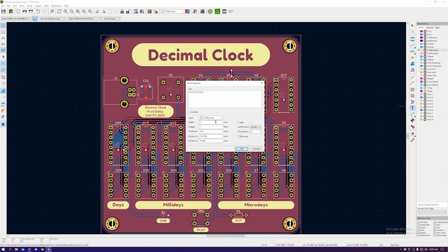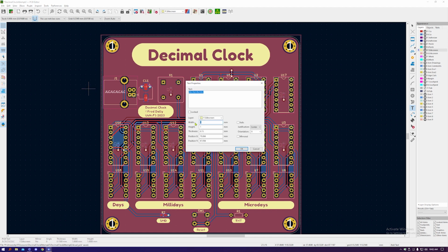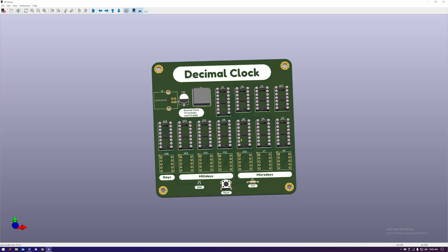And some people don't like that they do this, but what they'll do is they'll then go in and edit the Gerber file, which is how you export this, and they'll put on their little number in place of where you've put this. So what I'm going to do is I'm going to put it probably here. I'll make it a little bit smaller as well. Let's go for 0.8. And that means that their number will be hidden by the USB connector once that's been put on. Save, Alt-3, check it out.